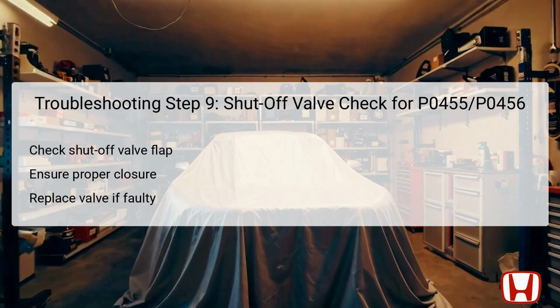In the 9th troubleshooting step, check the flap of the shutoff valve to ensure that it is properly closed. The shutoff valve is critical for controlling vapor flow. If it is stuck open, it could permit vapor leakage, triggering DTCs like P0455 and P0456. If the flap is not closed appropriately, immediate replacement of the main flap unit is necessary to restore full functionality. Ensuring that this valve operates correctly is crucial to maintaining the EVAP system's integrity and preventing any further emissions issues.